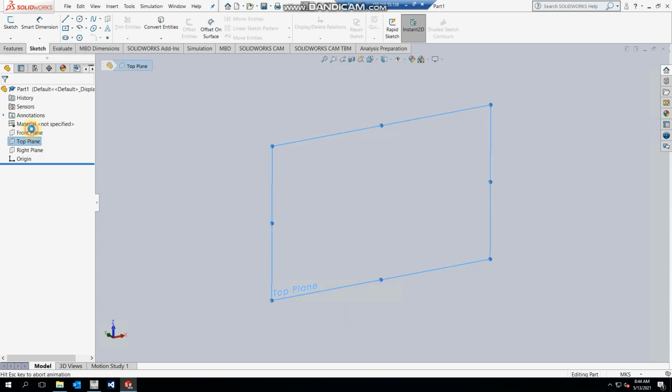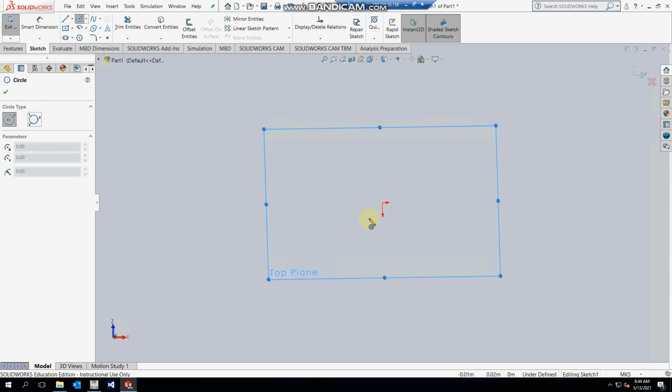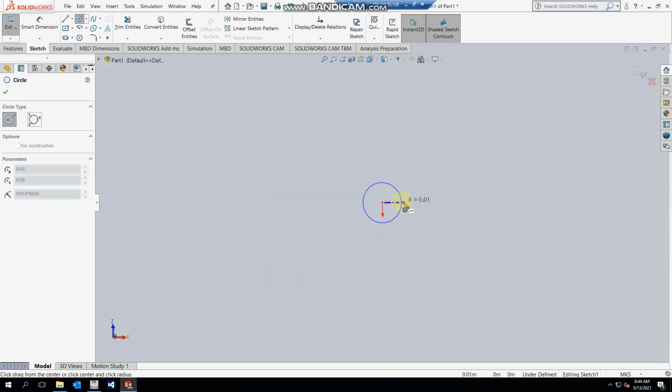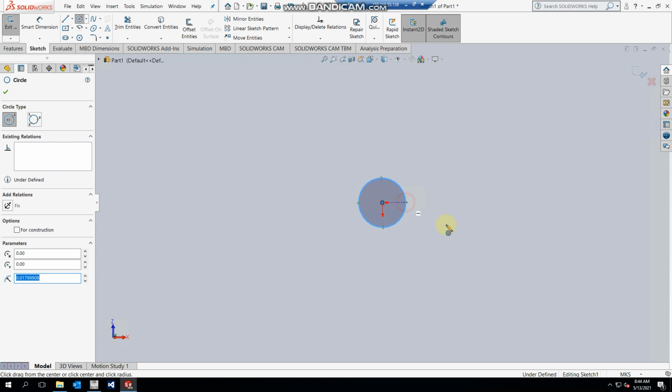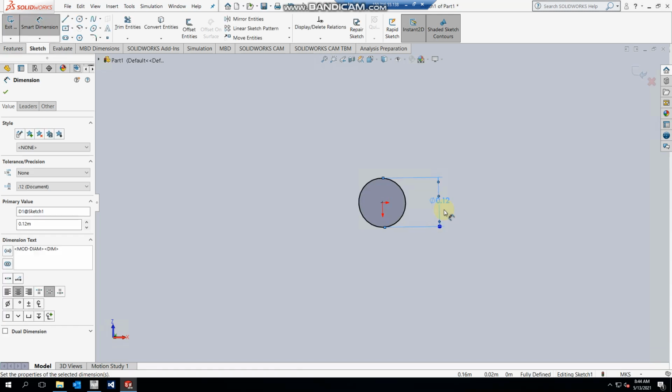And typically that's in the top plane. So, top plane, again, remember that it's going to be rotating about the y-axis, and what we're looking at right now is a side view. So I'll come over here and sketch a point on this circle. I'll sketch a circle, maybe radius of 0.12 meters, and also make sure, down here, that the units are meters, kilograms, seconds.